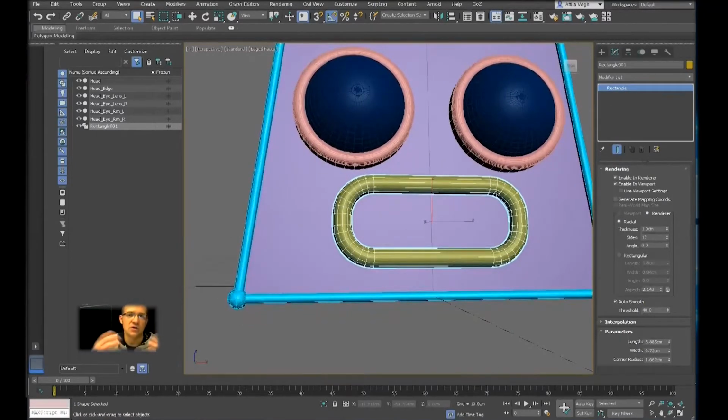Okay, and our task now is to create teeth for this. If you want to make it center, we have to switch to move mode because that is about a transformation. So W is for the move mode, or you can choose the icon here. And whenever you switch to any type of transformation tool, this area at the very bottom becomes valid. So can you see the values here?